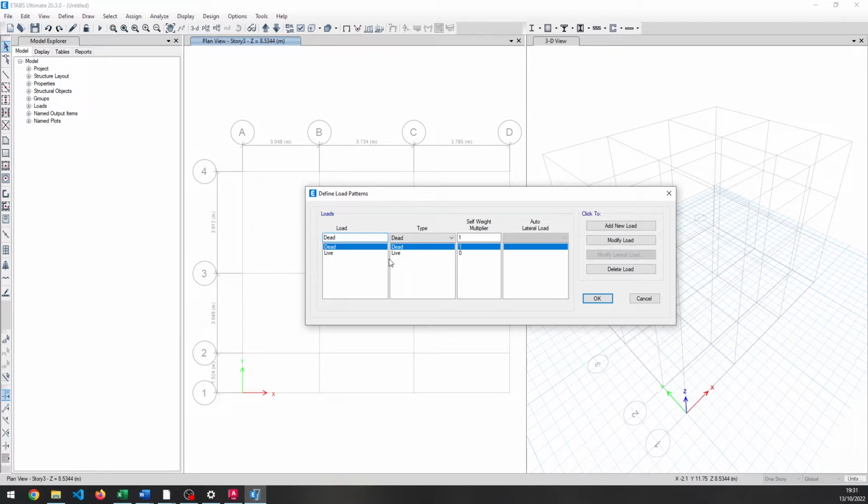So basically for the dead load, the software automatically takes the value, I mean the weight of the beam, column and slabs. So we have to leave it as it is, so the one denoted. For the live load, we're going to keep the value as per the NBC 105 2020 code. And for now, we're going to define the rest of it. There are many loads that act as a type of dead load, that is wall load, partition load, floor finish load, staircase load.